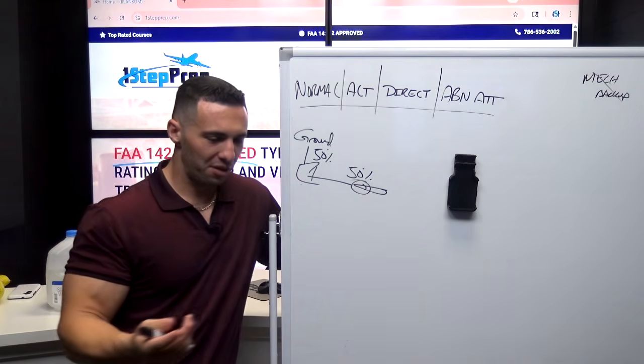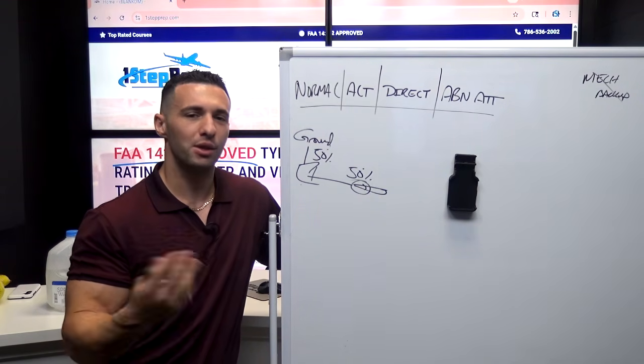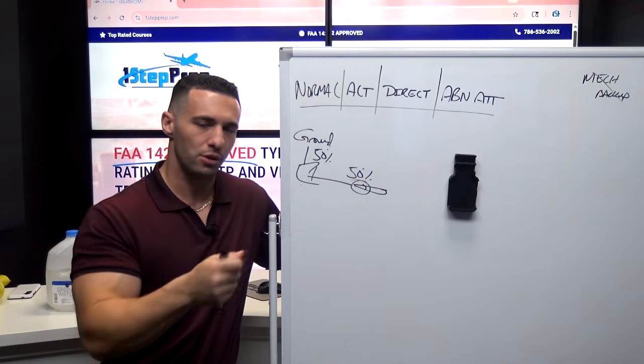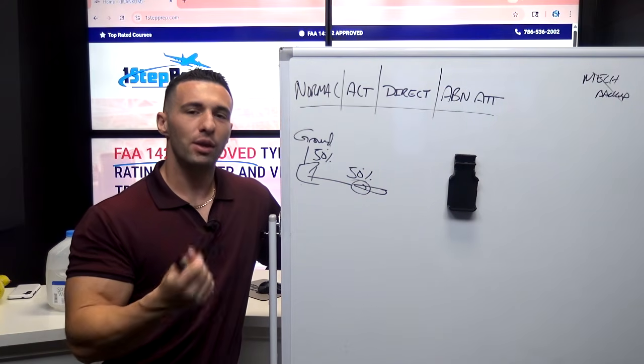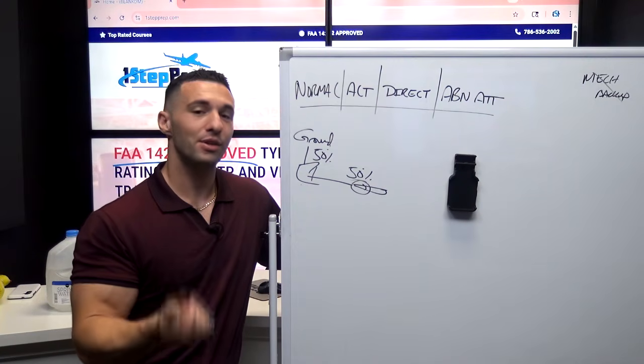The second thing, of course, is I've got to do a flight control check, which we usually do on the taxi out: full up, down, neutral, left, right, neutral. And the only way for the elevator motion to happen is if I have a direct communication.